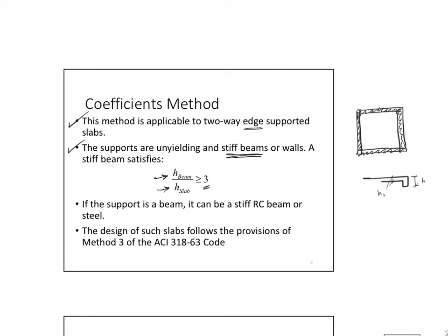Then what if I don't have this? What if I have a really small beam that is not as stiff or strong enough to be called a beam? In this case, we will simply see that the behavior of the slab is to take the load directly, because the slab now becomes stiff enough. It will take the load directly to the column without counting on the beam. And then the load path in this case will not be the clear, nice load path that we all want and desire for our two-way slab.